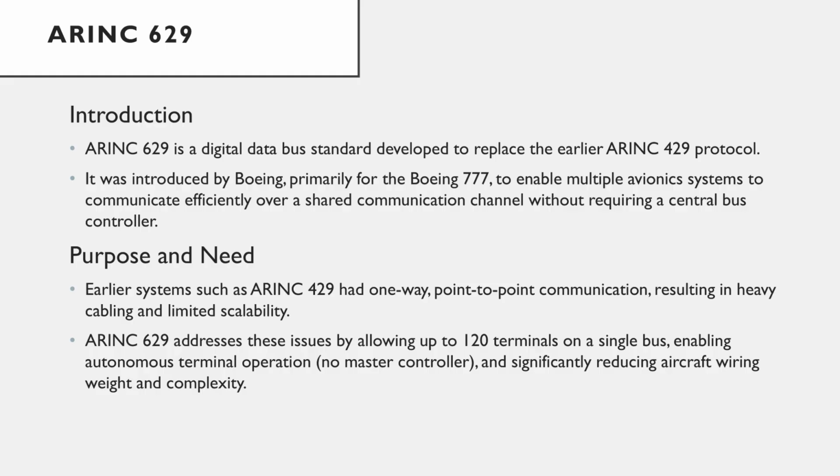Earlier systems like ARINC-429 relied on single-transmitter, point-to-point links. As avionics became more integrated, especially with fly-by-wire systems, these networks suffered from wiring complexity and limited data flow. Boeing initiated the DATAC program, or Digital Autonomous Terminal Access Communication, which evolved into ARINC-629. Its goal was to create a multi-transmitter bus with deterministic timing and terminal independence.